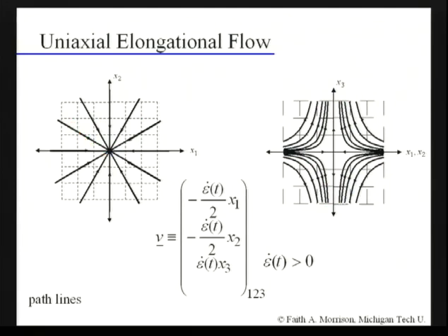Now, this is a very complicated looking flow, although it's maybe understandable to you because it makes sense to include a kind of a stretching flow. But unfortunately, we were not able to define a very simple, one-dimensional stretching flow. Nothing that looked nearly as simple as shear flow with one velocity component. We needed 3. We needed to stretch and then have the flow contract in the other direction. So elongational flow is naturally more complicated than shear flow. It's more complicated and it's also very severe.